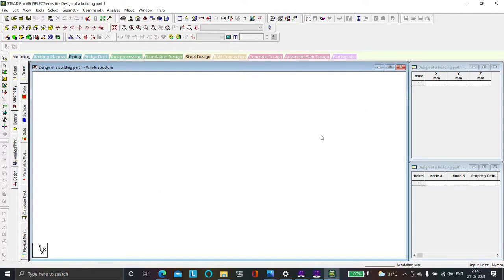So what we see here is the main setup of Staad Pro. We have got options here. Some of these are shortcuts. So let's start by knowing some of the most important options here. We've got this model, this part says add beams. This is what we select when we want to draw a beam. So every beam that we draw, whether it's a standalone beam or a beam as part of a structure, before we draw it, we select here.